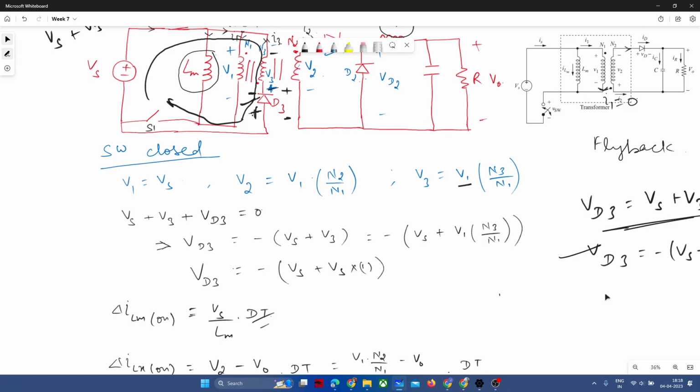Generally, power is developed in a magnetic circuit based on your magnetic flux density, how much is the magnitude of magnetic flux density, into how much is the electric loading, that is current. So if you increase the magnetic flux density in the circuit, you will require a very small amount of amperes in that circuit to generate your desirable power. If you have a weaker magnetic field, if you cannot afford a strong magnetic flux, then you will have to compromise on the electrical side and supply a higher magnitude of electrical current, and that eventually will create huge copper losses and other losses related to your electrical side. So that's why we want to maintain the balance between the electrical, meaning conductive, and inductive side.